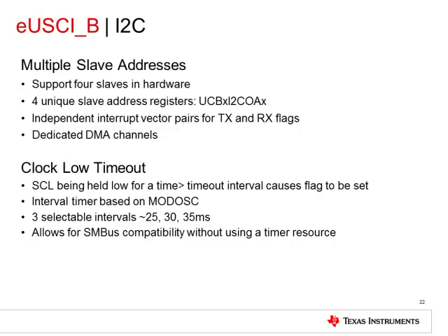The registers I2C own address 0, own address 1, own address 2, and own address 3 can contain 4 different slave addresses. Up to 4 address registers are compared against a received 7 or 10-bit address. Each slave address must be activated by setting the enable bit in the corresponding address register.